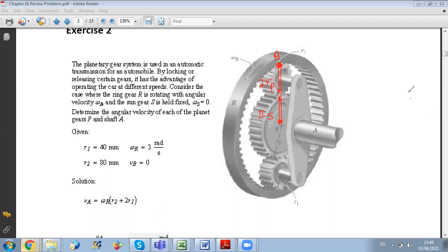Okay, so if I draw my gear P, this gear P has a point of zero velocity at A, so VA is equal to 0. While for point B here, to know the direction I need to use the right hand rule. The point's velocity is perpendicular to the radius, and since omega is counterclockwise, VB will be directed towards the left, and I can write that VB is equal to